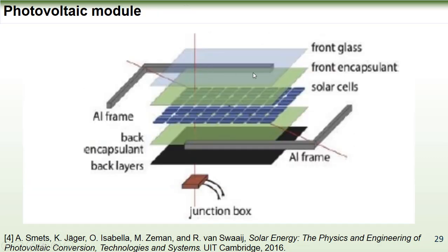A typical PV module, which usually has a 25 years lifetime, consists of several layers. At the center, the solar cells, sandwiched between 2 layers of materials such as ethylene. Different manufacturers have different materials, of course, with a layer of glass to allow the sunlight into the cells, and a back layer of plastic or other material to protect the cell from humidity and other types of stress, surrounded by a frame typically made of aluminum to enhance the mechanical strength of the module.